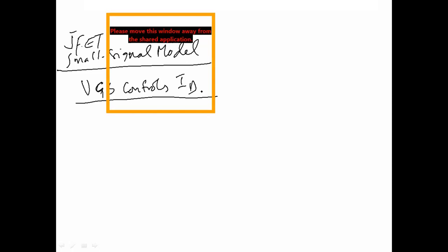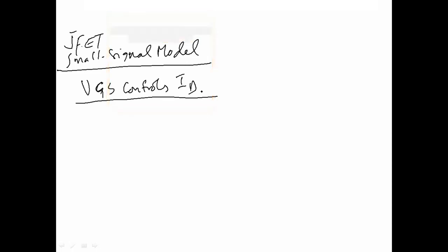So we studied in chapter 7 that DC gate to source voltage, VGS controls the level of drain current. And this relationship was defined by Shockley, and the equation is so called the Shockley equation. So Shockley equation is applicable to JFET and D MOSFET and D MESFET. What is Shockley equation?